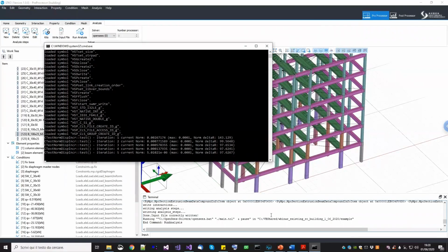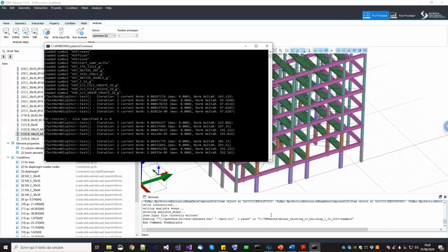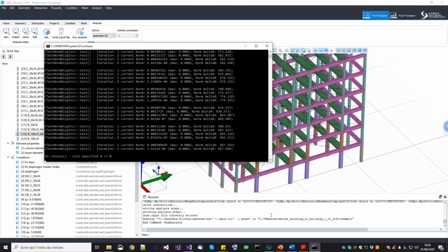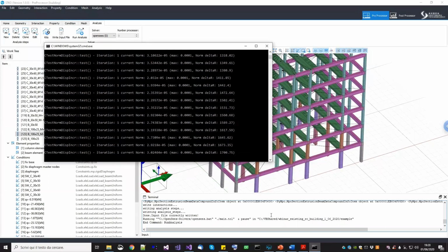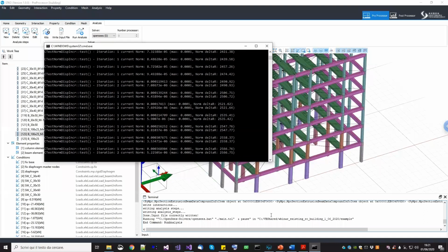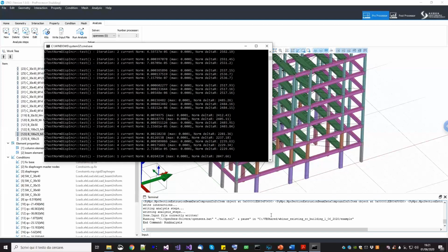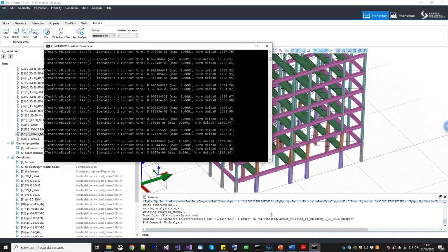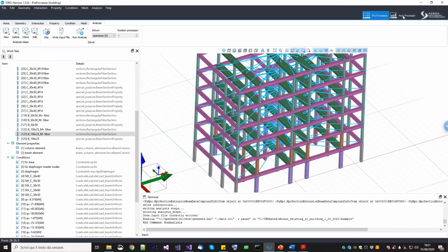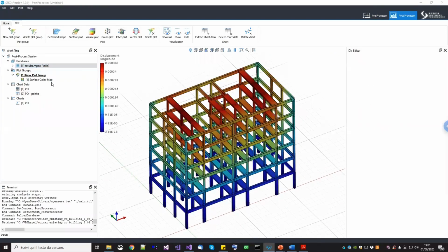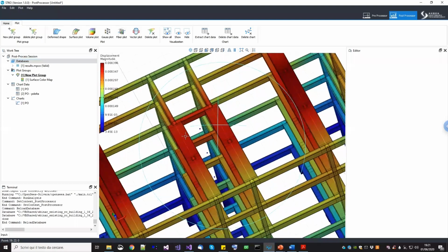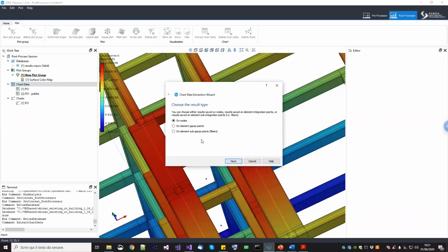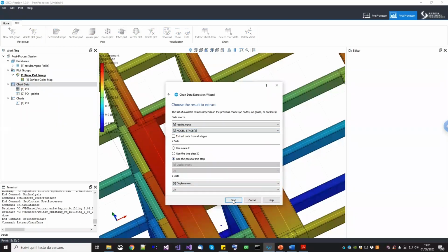And we are going to compare the curve, and finally, I will show you this new tool to create the beam column joints. Let's give it a couple of seconds. It's finished. Go back to the post-processor, reload it. And now we are going to extract once again the pushover curve. So I select this node, extract chart data on nodes, stage number 2, displacement, pseudo time step, next.